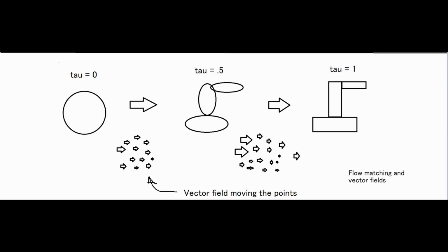But just having a noisy action chunk is not enough, because there are many, many paths in high dimensional space which can give an action chunk that looks like that. It is okay to set up the model to try to predict the noisy action chunk at time tau, and then keep having it predict the next denoised action until you're at the target distribution. This is essentially what diffusion does. But there is a better way to predict this action chunk.